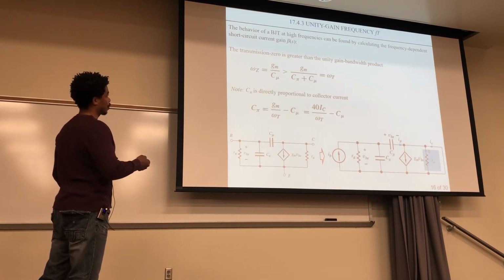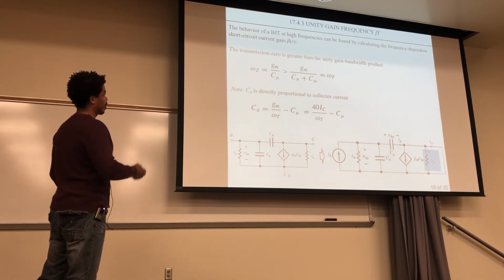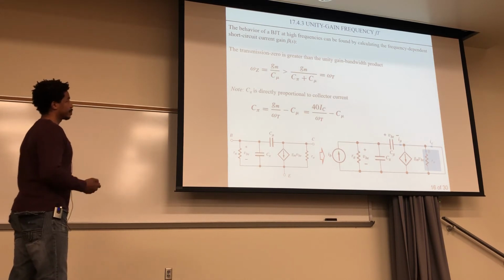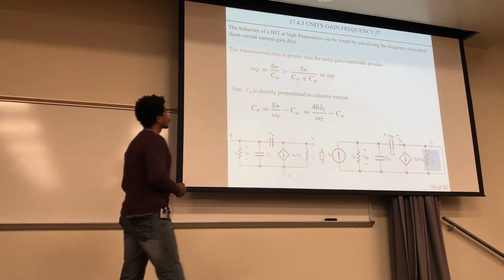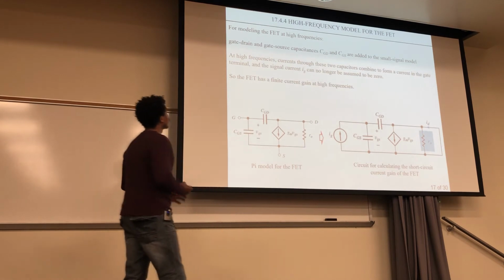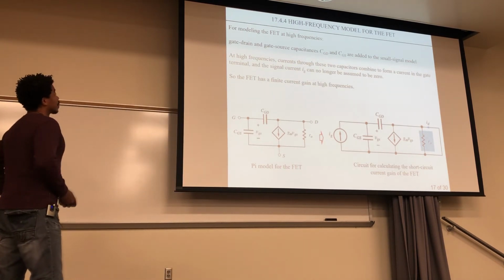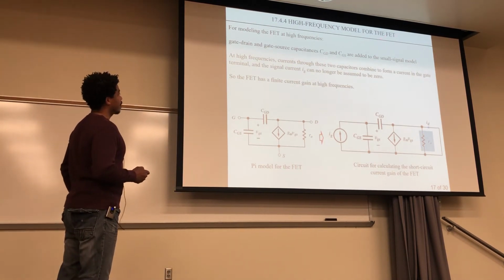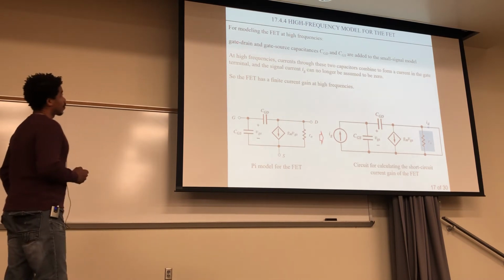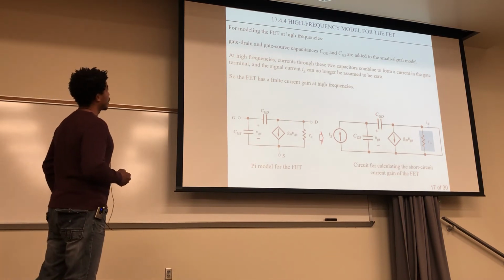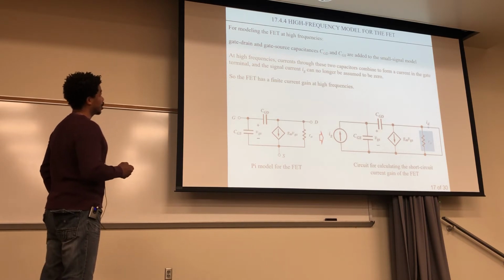All right, so high frequency model for the FET. For modeling the FET at high frequencies, the gate-drain and gate-source capacitances, that's CGD and CGS here and here, are added to the small signal model. So here's the small signal model, and then we'll add these here.